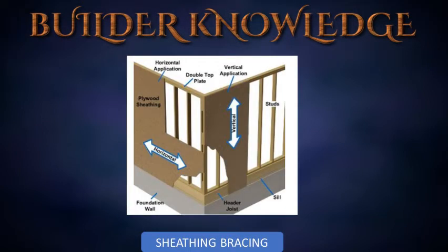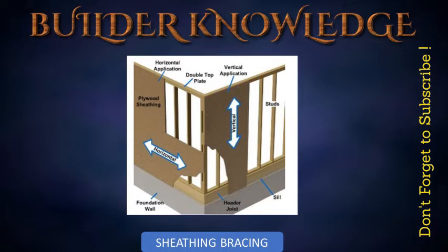Plywood sheathing. Yes, plywood sheathing is used to brace the walls also. It has the highest strength out of all bracing. Each board acts as a brace of the wall. Other types of bracing may not be necessary if plywood sheathing is more than half an inch thick.